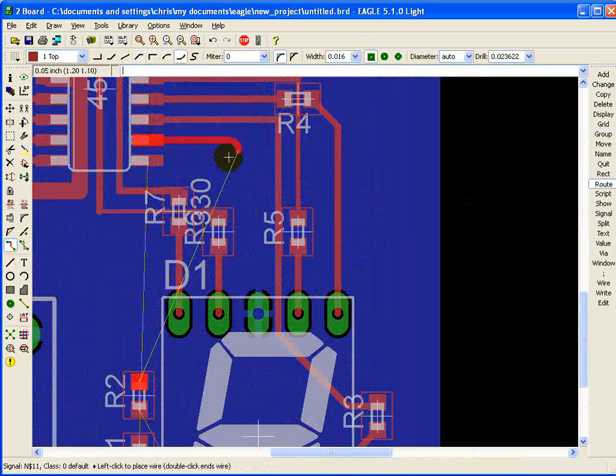Now one thing, if you're going to do high-speed designs, which this obviously isn't, you need to be careful about 90-degree bends in your traces. They'll cause some signal integrity issues, and you'll start losing your signal really fast. Bring that guy through. Oops, did that with the wrong one. Back up a little bit. Thought I had this guy.